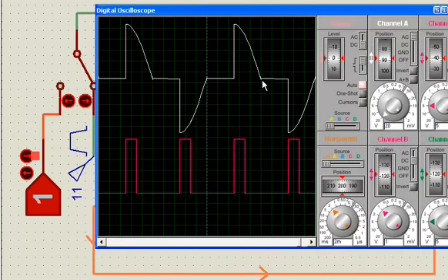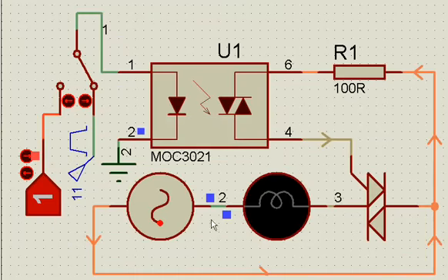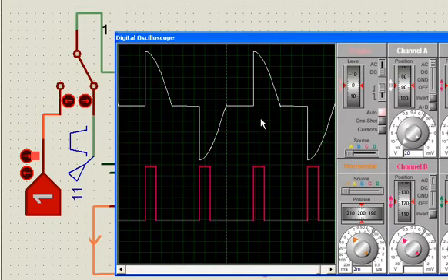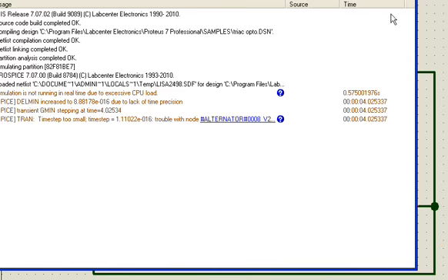For the negative half cycle also, in a similar way, the pulse comes after 5 milliseconds. So in the negative half cycle, this goes this way and waits here, because the light is still not falling. The light is falling after 5 milliseconds. After that, this goes this way, and the path is complete. Once the triggering path is complete, the main path flows, and that's how the lamp glows, and we get a waveform of this nature. This is the type of waveform that we see.